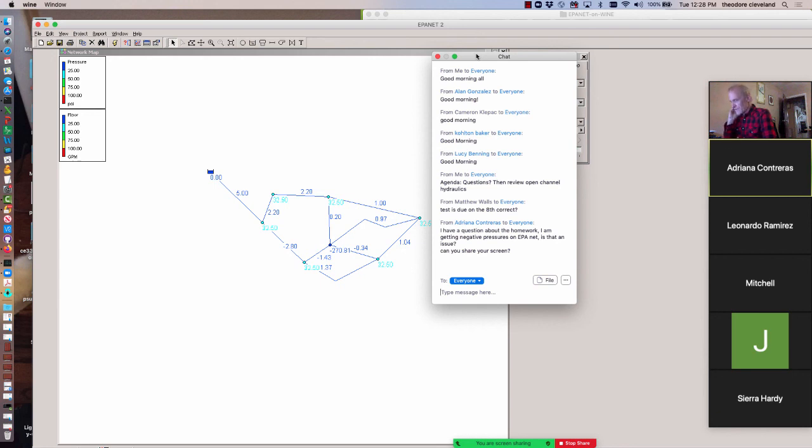The two problems can both be done with that. The first one's easy. You do pretty much just what I did here. Go ahead and attach a reservoir to node 1, jack with the reservoir until you get the pressure at node 1 to, I think that's at 100. I get the head at node 1 to 100 feet and get the other nodes and you're done.